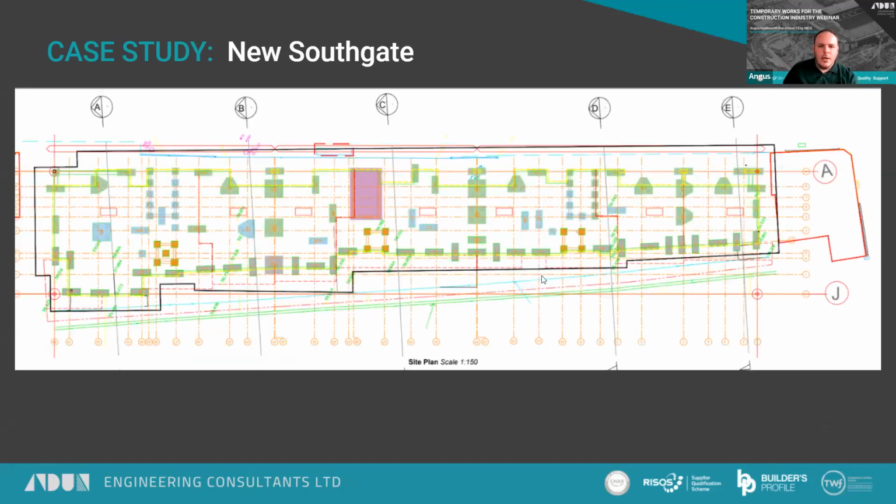And then when you overlay the plan, this green line here is the toe of the wall, the blue line is the site boundary or the Network Rail boundary, and you can see how close we're getting with some of these piles. I suppose it's a relief that they went with a piled foundation and not with a raft, because that could have been awkward.